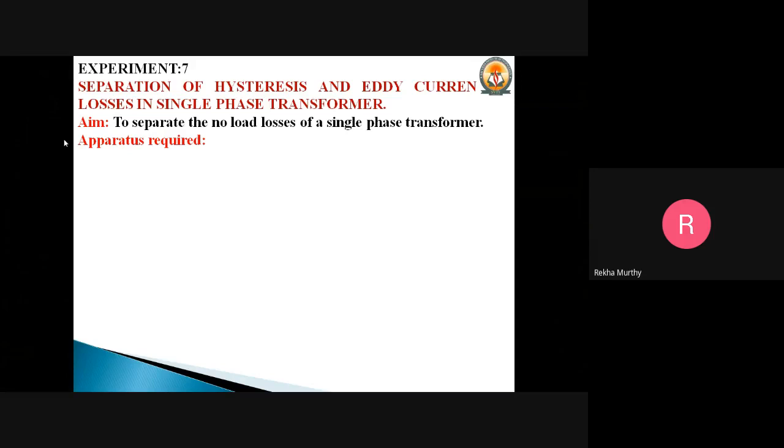Fine. One more thing you require is the motor generator setup, which should be connected on the primary side of the transformer. In the motor generator setup, we usually take a DC motor, because the alternator can be driven by the DC motor, with DC excitation on the rotor.